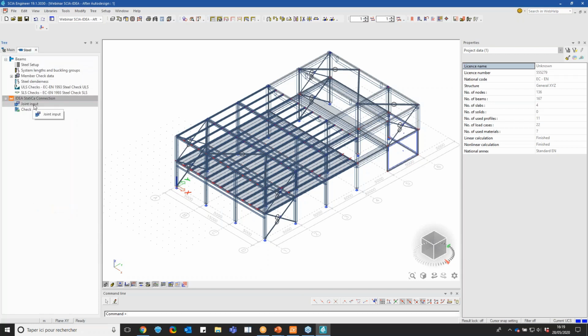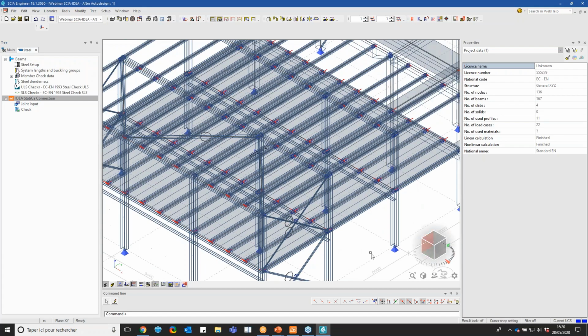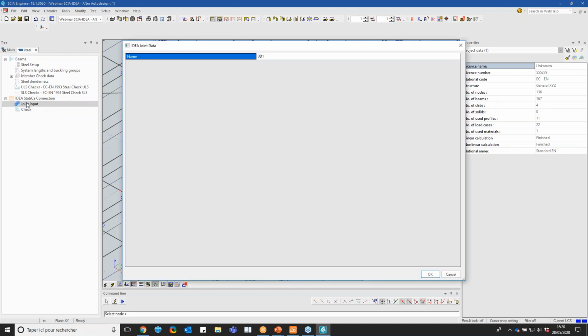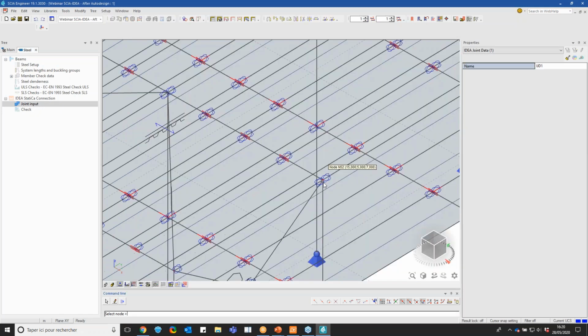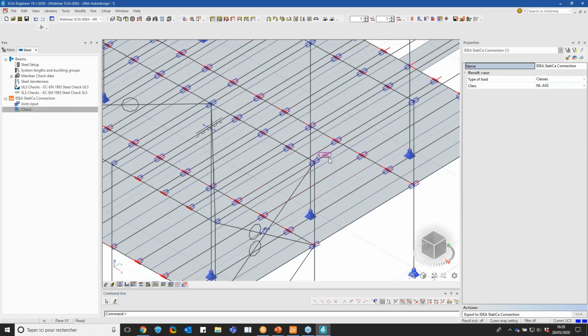In this case, what I did was I'm going to pick a node. It is already prepared, so I will focus on this one. I need to ask for the joint input, so that's quite easy. I just need to select it. Once I select it, it will show all the elements connected to this element, and I can go through the check. In this case, I can export either all the combinations. So in this case, I can go through combination, nonlinear combination, or all the classes.